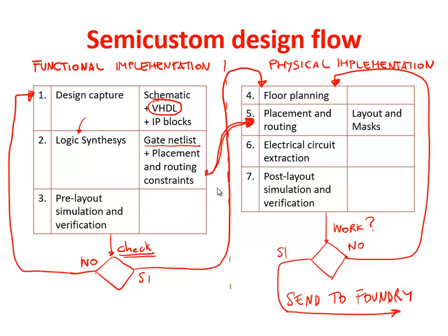Then when I have the gate netlist, I can simulate the total circuit at the gate level and check if the function of the circuit is what is expected from specifications. So at this point, after the logic synthesis, I can perform some simulation of the circuit.